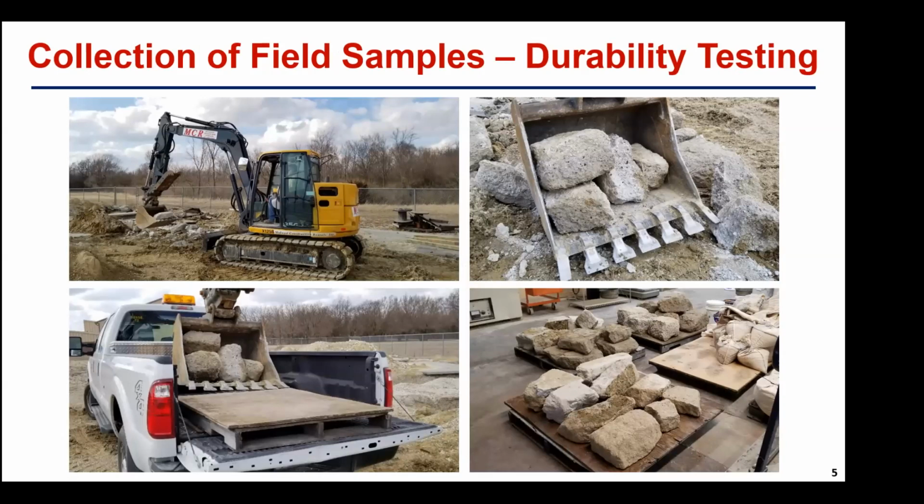If we try a dry coring method, on the other hand, so that we don't use any water, because these materials are not very fine like concrete, but they are actually a little bit rough on the surface. They actually create very high friction and they get confined into the drill bits, and it's very hard to also get an intact sample out of the drill bit for testing.